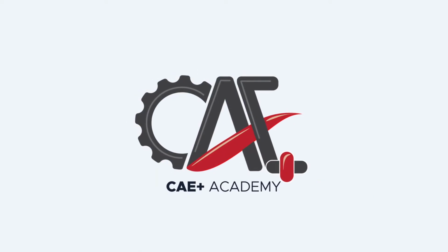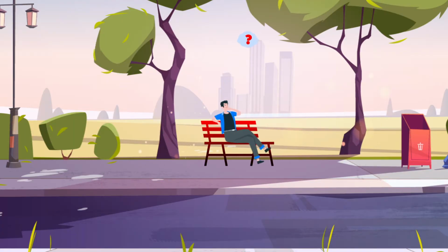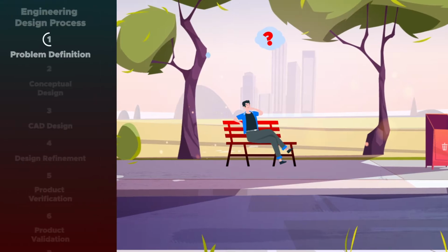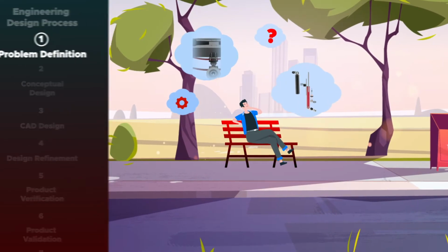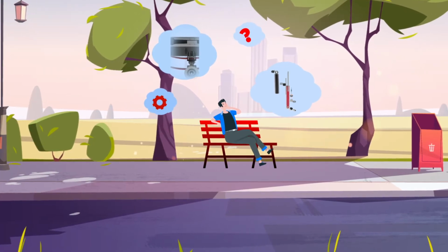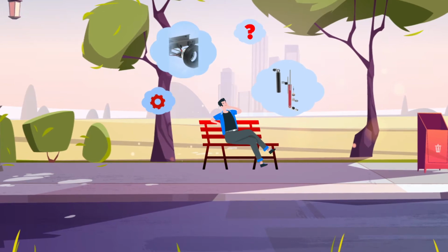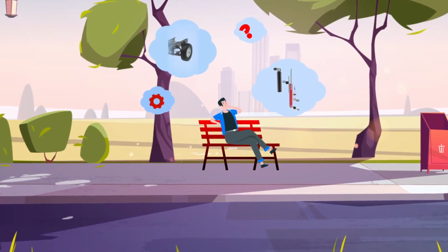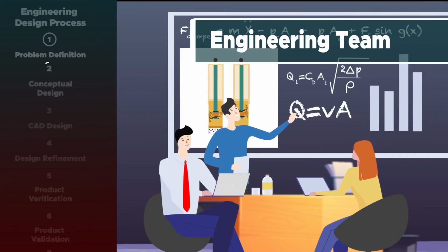Crucial to solving any design problem begins by asking the right questions. Like, how can we improve the ride quality of a truck suspension system? One solution can be found by adding a shock absorber between the chassis and the wheel assembly to absorb or dampen the compression and rebound of the springs and suspension. In short, the engineering design process begins by defining a problem and completing background research on the problem. The second step will be the conceptual design.